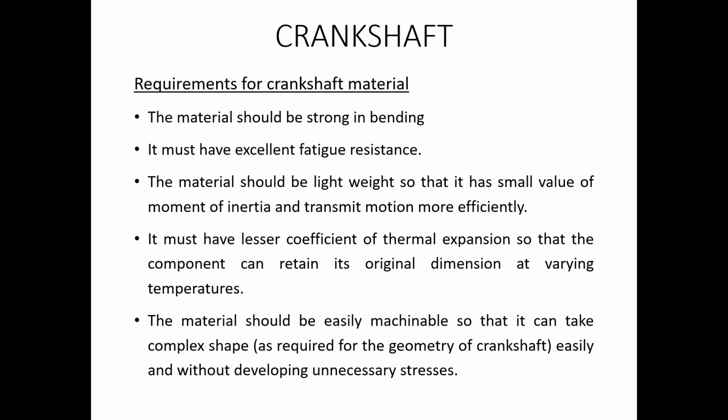And since it experiences cyclic loading, it experiences both bending as well as tensile stresses simultaneously. So that is known as cyclic stress. So the crankshaft usually undergoes cyclic stress, and whenever a material undergoes cyclic stress for a long period of time, there is a chance that a fatigue failure can occur.